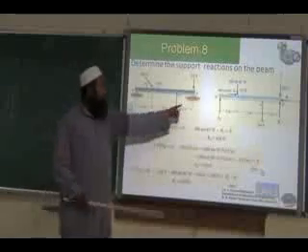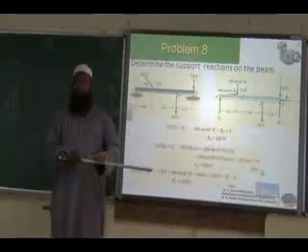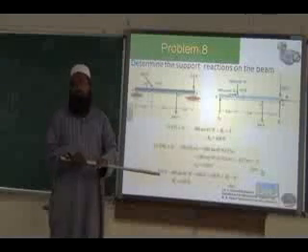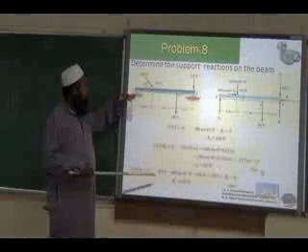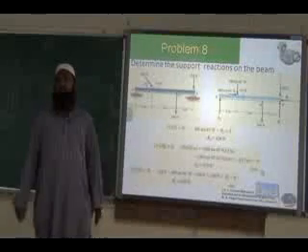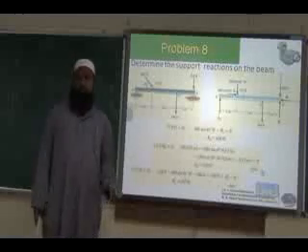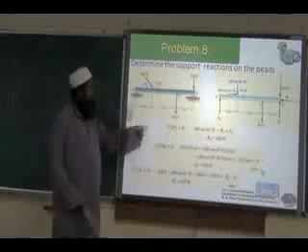That is why we have two forces here. Here no bolt is there, only a flat surface on the ground. Okay, on the fixed support. So it can slide in x direction, but it cannot move in y direction. So that is why we have only Ay.